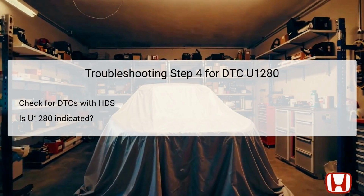At this point, it is essential to check for diagnostic trouble codes using the HDS again. This verification step determines if DTC U1280 is still present after the previous procedures. If the U1280 code reappears, it confirms that the communication bus issue is persistent and requires further investigation.